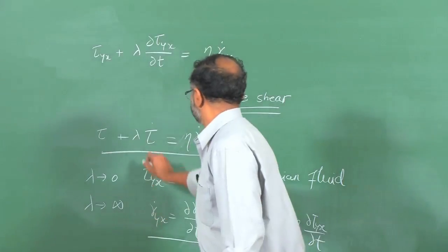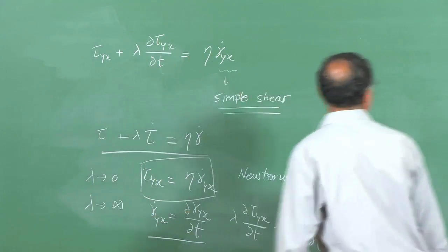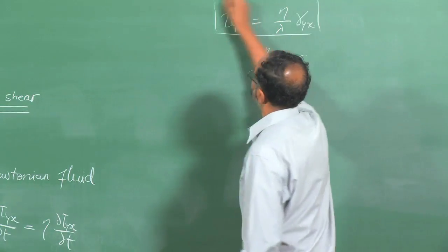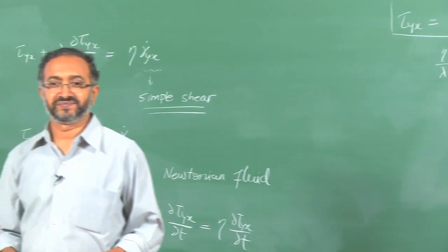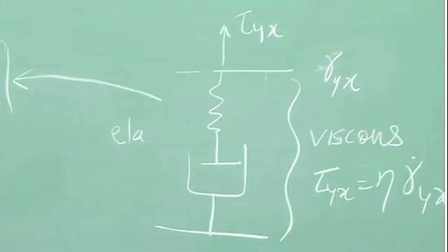It says that this is the relationship for fluid, it says this is the relationship for elastic solid. Let me combine the two, and therefore I will get viscoelastic response. Many a times mechanical analogues are used to describe the viscoelastic models. These serve as representations of how viscous and elastic response is combined in a given model. For example, Maxwell model is a series combination of spring, which represents elastic response, and a dashpot which represents viscous response. These analogues are also useful to understand how to arrive at different terms of a given model.